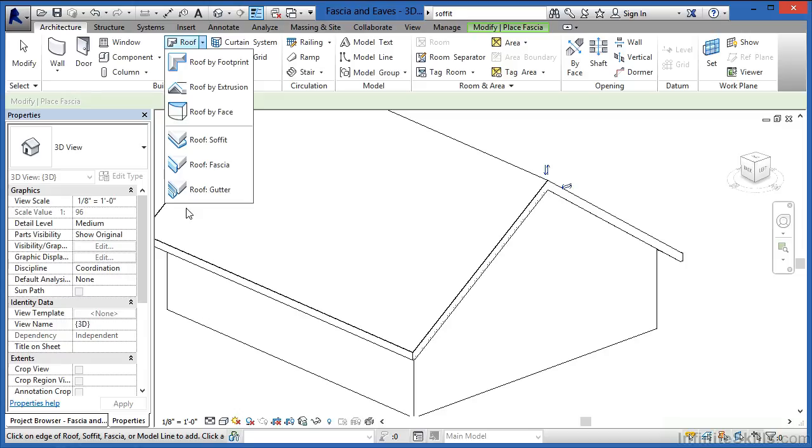One last thing, this thing that's a roof gutter, it applies the same way as how the roof fascia works. You'll just simply select on roof gutter and then pick where you'd like its base point to be, such as maybe the top of the fascia board, and then it would place a roof gutter in all the locations you'd want the roof gutter as well.